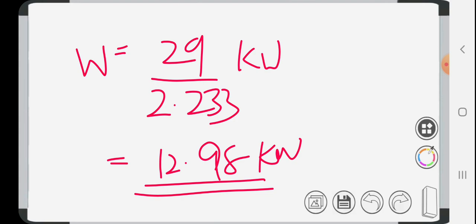In the problem, the name Carnot was nowhere specified, but you have to understand that this problem is based on the Carnot cycle, because in that problem a word called ideal COP is specified. So ideal COP specified means you are supposed to use the equation for COP in case of the Carnot cycle.